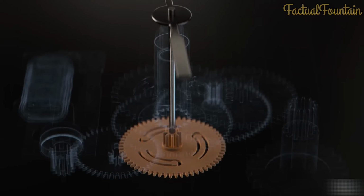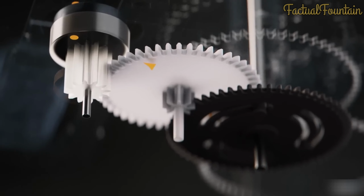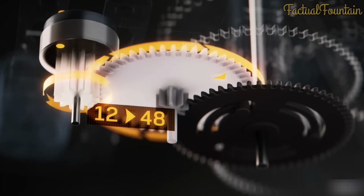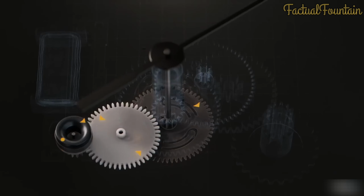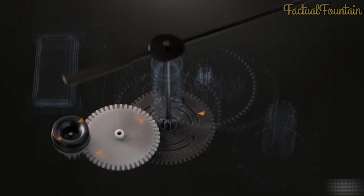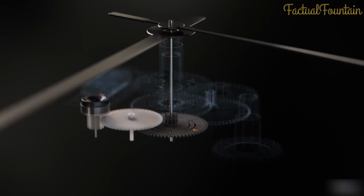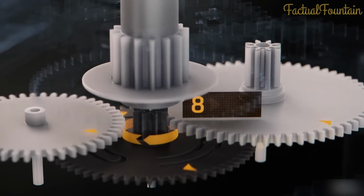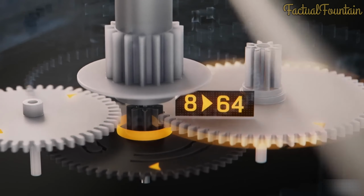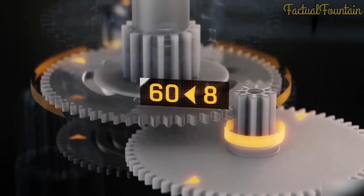To move the second hand, which is mounted on a shaft through the clock center, we go through a 12 to 48 gear reduction and then an 8 to 60 gear reduction, thereby reducing 1 revolution every 2 seconds down to 1 every 60 seconds. The minute hand is also mounted on a shaft through the center and is driven through an 8 to 64 gear reduction to the idler, followed by 8 to 60 to the minute hand.